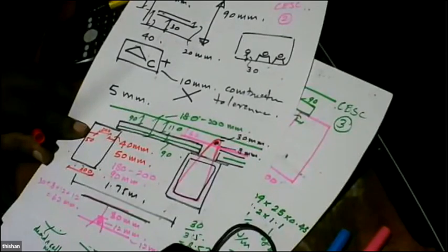The reason is, if you have a thick slab, 200 or 180, cast in one operation, finite element works fine. But in our situation, we have a deck slab that is cast in two separate operations. So because of that reason, we have actually done load testing and worked out the reasonable values for load sharing. So, any other question?